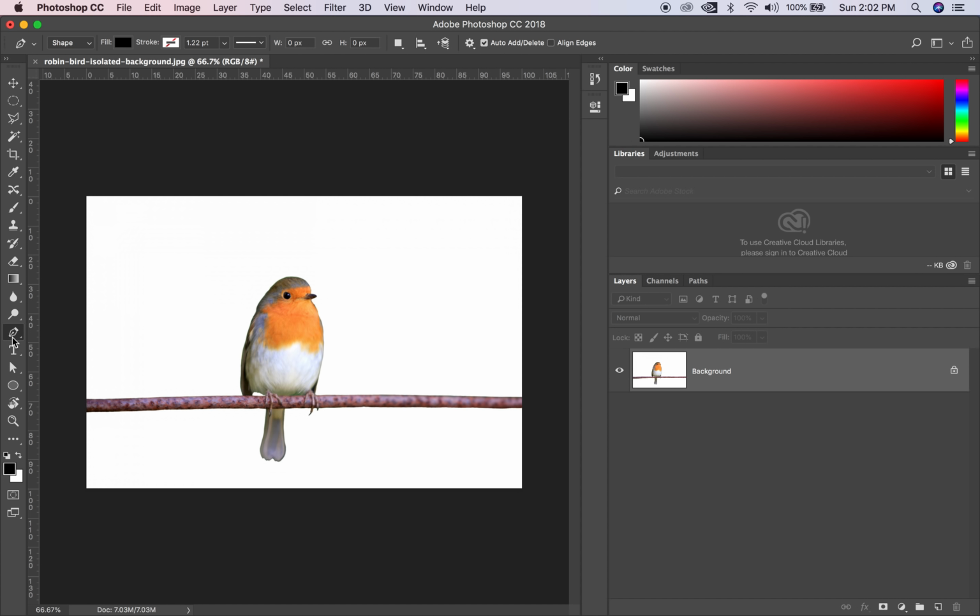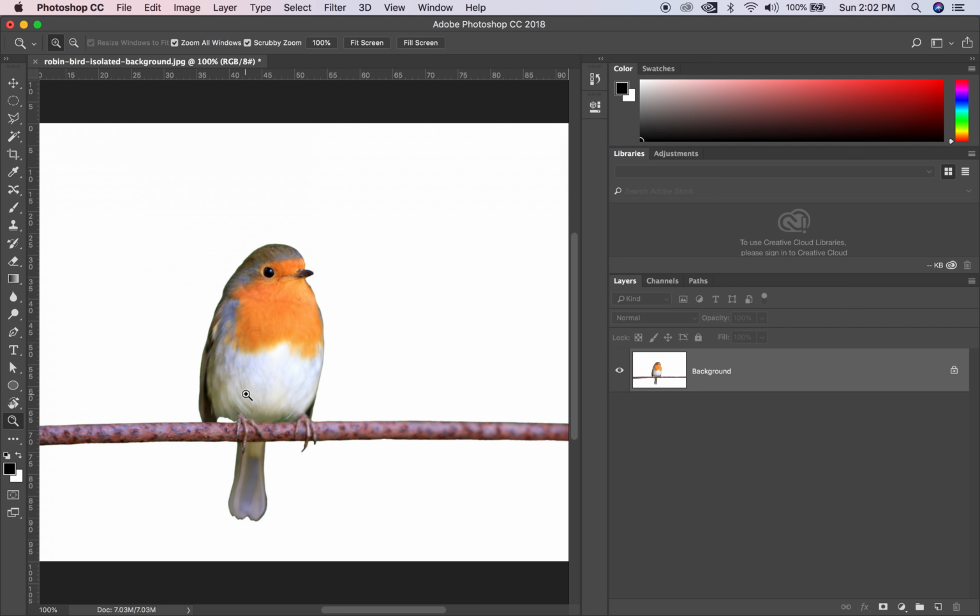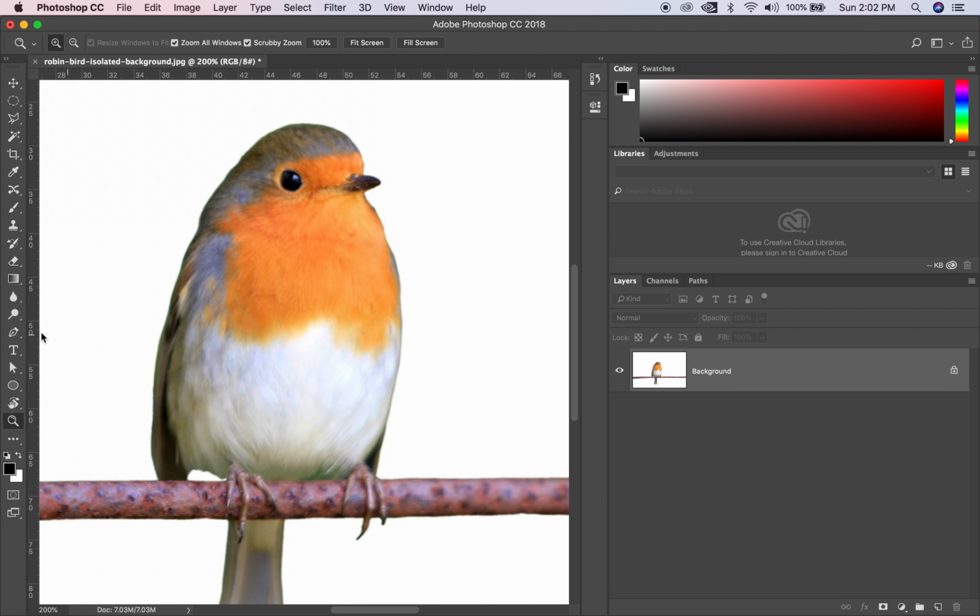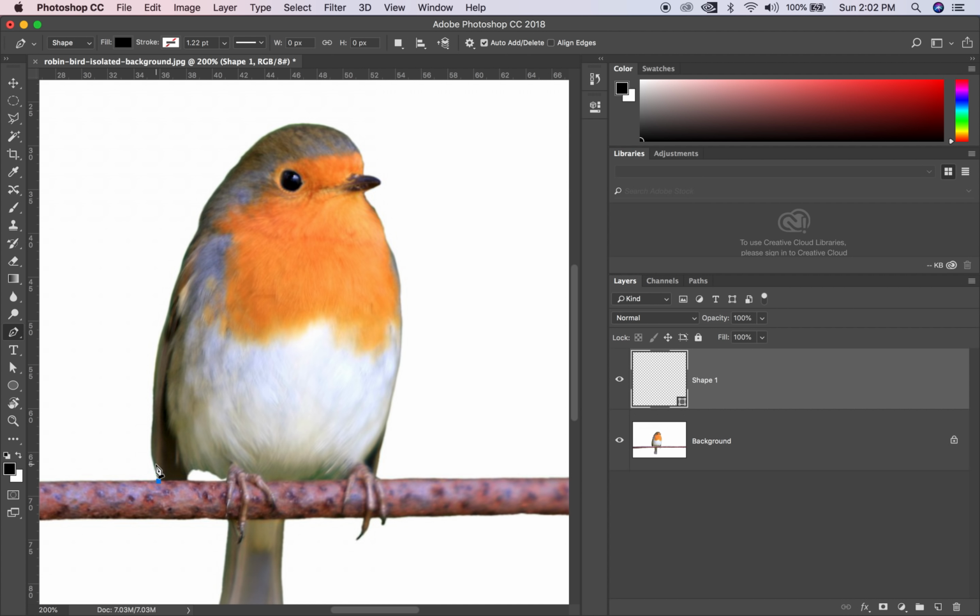All right, so how do we use this pen tool to create a really custom shape? Well, the pen tool is one of the most powerful tools in our arsenal. So what we're going to do, and this is the assignment for you for this project, is I want you to make a silhouette of what you see on the screen. Most people will sit here and draw tons of little points, but I want you to remember your pen tool is pretty powerful. So if you draw a point and then drag and aim the handle, you can actually get some pretty cool things. But then you're going to get to a point where that handle just doesn't want to cooperate. And so if I click my Alt key once, it removes that handle.